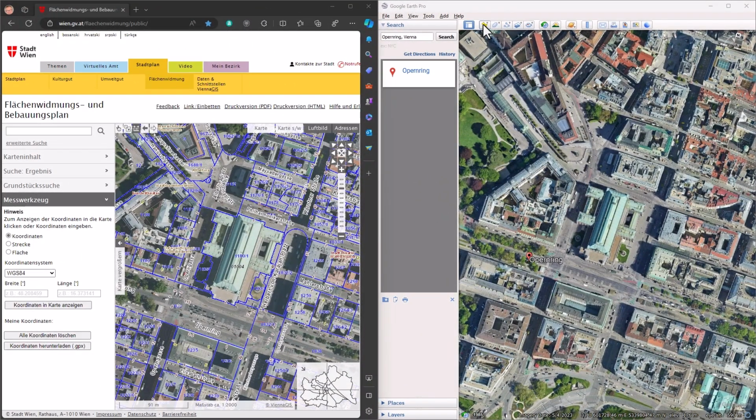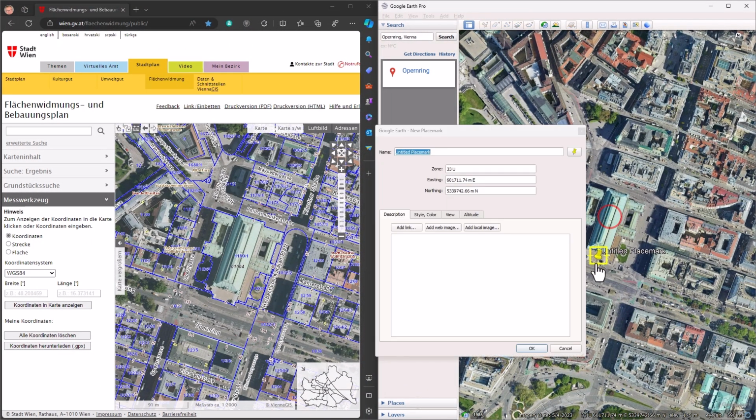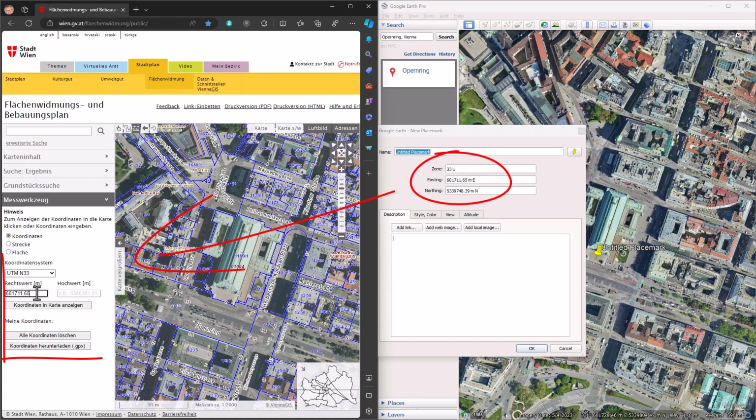There are many other systems besides these. For example, if you locate the Vienna Opera House in Sector U33, the offices in Vienna use the so-called Gauss-Kruger coordinate system instead of the UTM. For this, first enter the UTM coordinates, then simply switch to the local system.